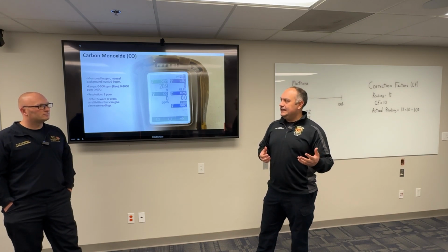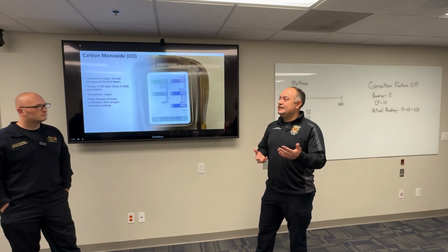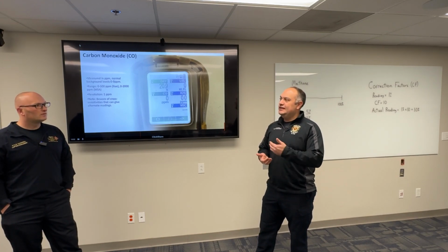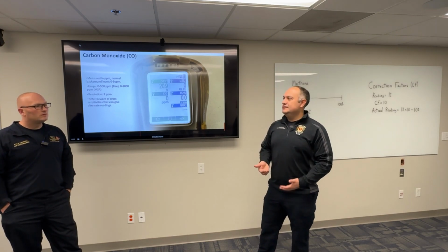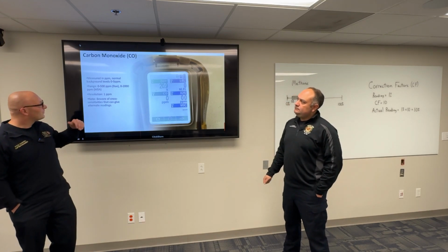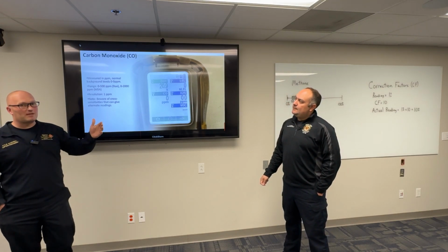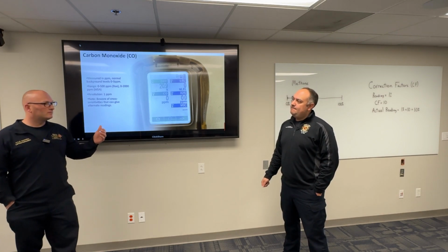Yeah. So in that case, the CO sensor thinks it's seeing CO, but it's cross-sensitive to hydrogen, so it's going to think it's seeing CO, and it's going to give you readings, even though there might not be any CO there. So something to consider too. Not every call diving into this cross sensitivity. Are you going to get CO?